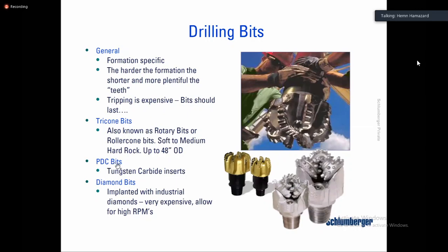Nowadays, we have drilled about 7 wells. For any well we drill after 7 wells, you have huge data about the formations and the performance of the bit and everything else. So now we can almost drill each section with one bit. We've achieved this, each section with one bit, no more.